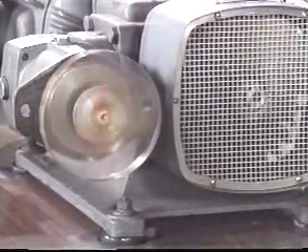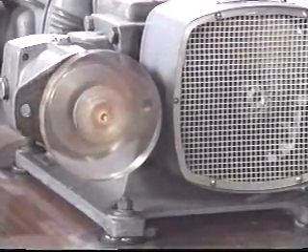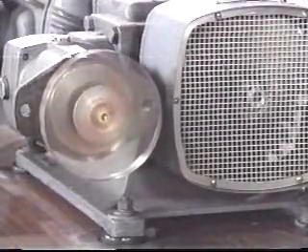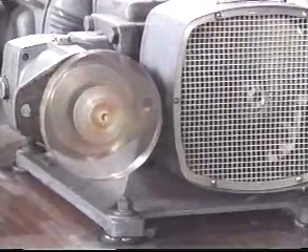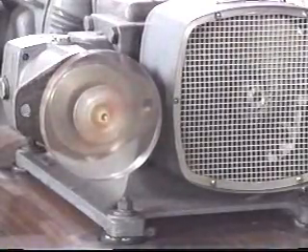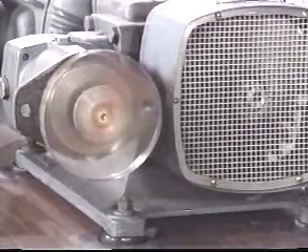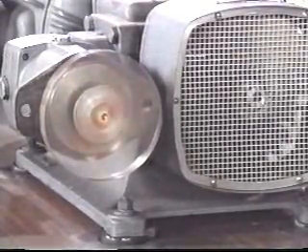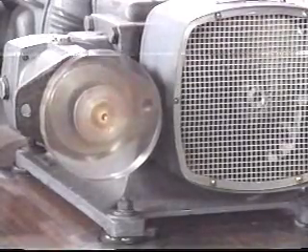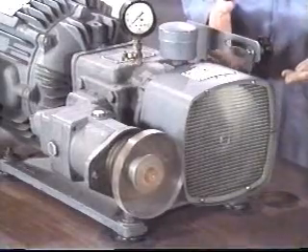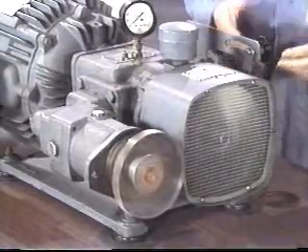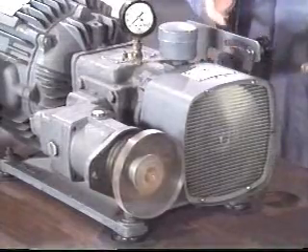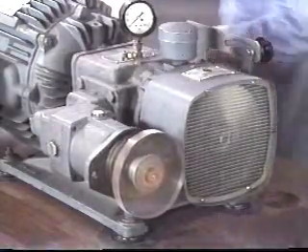Remember, the pump and motor in this unit have the same displacement, so the top speed of the motor would be essentially the same as the pump drive speed. If we were to install a larger hydraulic motor, it would develop more torque. But since it would require more fluid per revolution, its top speed would be slower. A smaller motor would, of course, turn faster, but develop less torque. In each case, however, the torque would be independent of speed.